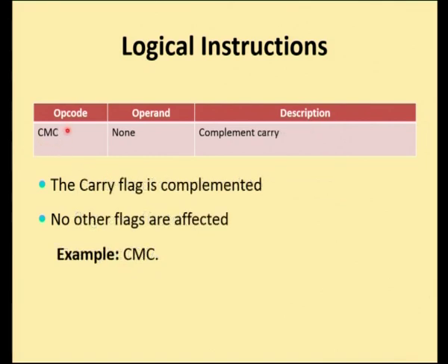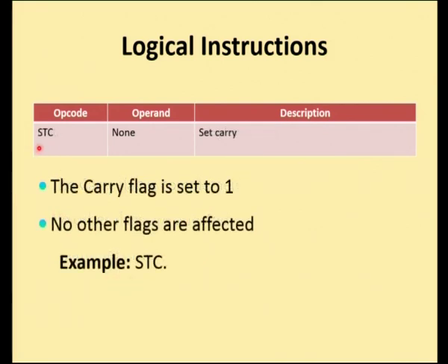The next instruction is CMC, which is used to complement the carry flag. Either a set value can be reset by using the CMC instruction. The carry flag is complemented, no other flags are affected by this. To set the carry, we can use the STC instruction.